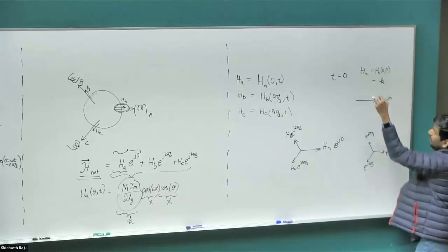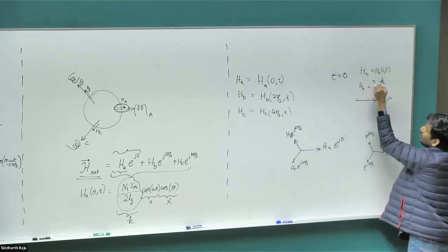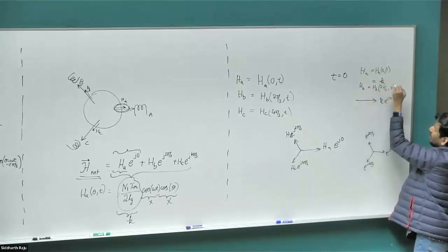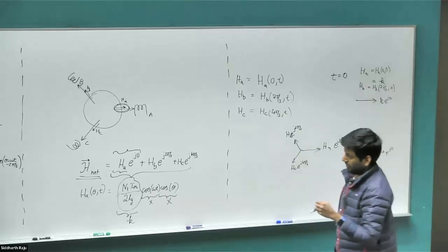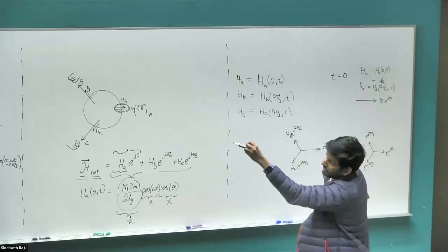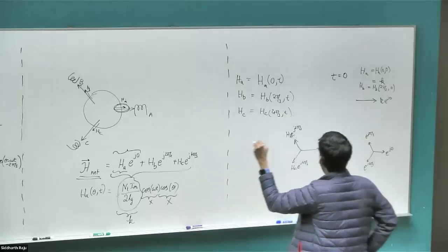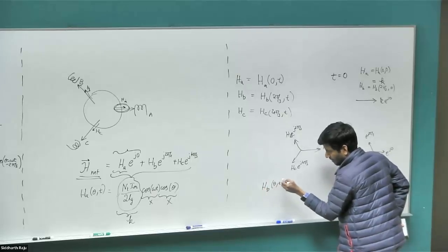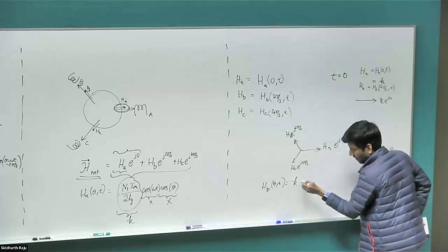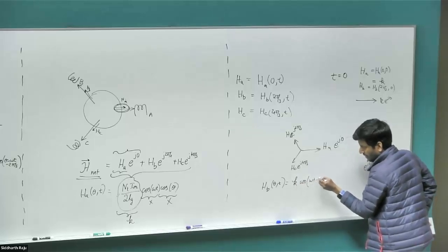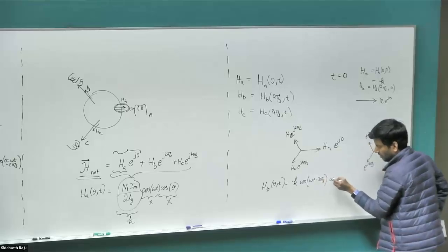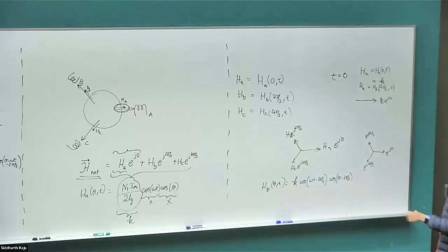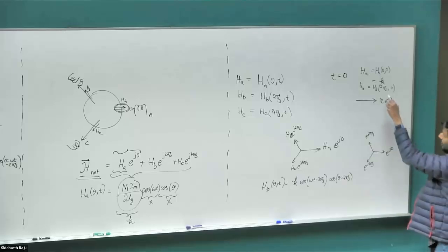It's just going to be 1 k times e power j0. Okay. So same time t equal to 0, let's compute what HB is going to be. It's going to be HB at the angle 2 pi by 3, time t equal to 0. So let's substitute the value in the HB expression which I have from there. So my HB of theta comma t was equal to k times cos of omega t minus 2 pi by 3, times cos of theta minus 2 pi by 3. So what is my theta? My theta is 2 pi by 3.